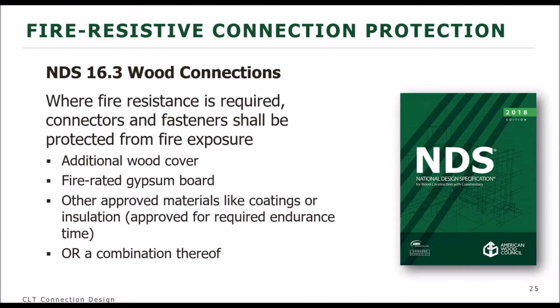We can provide it by providing additional wood cover beyond just the wood members in the connection itself. But it is important to note that we have to protect not only the fastener, but also the wood that is part of the connection. That's the part of the wood that the screw or the nail or whatever is biting into.